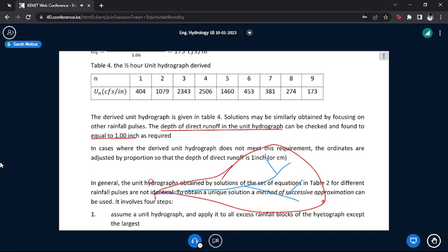Imagine you are looking at this catchment, and I'll try to draw it, although I don't know whether I'll manage, because I'm trying to draw a 3D kind of picture. If the discharge is a volume coming from this area, and you distribute the discharge all over this area, what depth of the catchment can it fill? That is the depth of runoff, the depth of direct runoff.